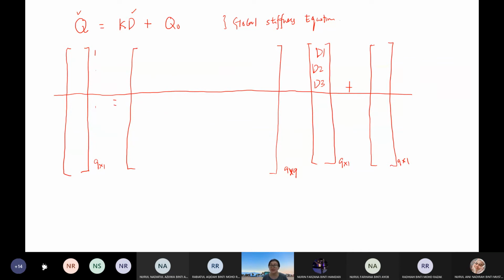So we need another vertical partition. And you must know that this K matrix is a square matrix. So if you partition at row number 3, you need to partition also at column number 3. So it will have a size of 3 times 3 matrix here. This region will be the elements that will help us find our unknown displacement. So we need to prepare for this.